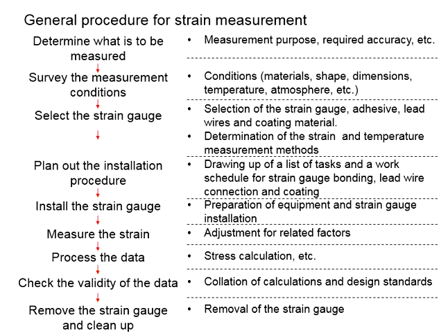Based on what you have observed during the testing, based on the failure mode of the test specimen, as well as based on the readings given by the other measuring device, you can do the cross-checking and you can more or less tell whether the data is logical and reliable.